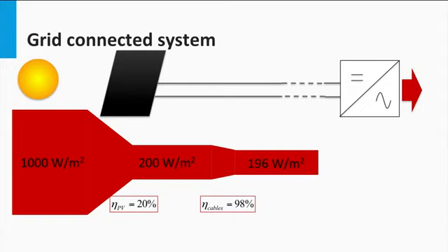With advancement in power electronics, it is rather common to have inverters that reach greater than 97% efficiency. However, usually the efficiency of the inverter is dependent on the power at which it operates. It is seen from practice that the inverters typically reach their rated efficiencies at around 50% of the rated operating power. For the sake of simplicity, we shall assume an average efficiency of 95% for the inverter.